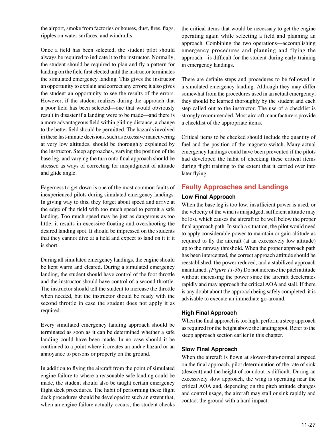Once a field has been selected, the student pilot should always be required to indicate it to the instructor. Normally, the student should be required to plan and fly a pattern for landing on the field selected until the instructor terminates the simulated emergency landing. This gives the instructor an opportunity to explain and correct any errors. It also gives the student an opportunity to see the results of the errors.